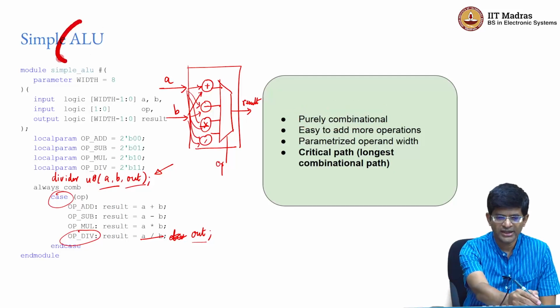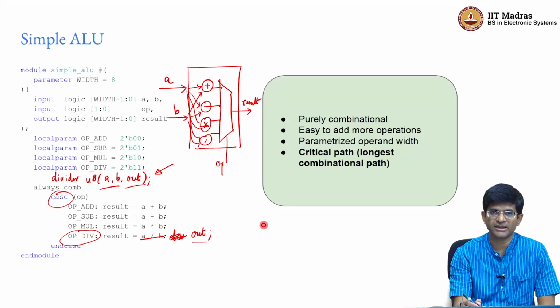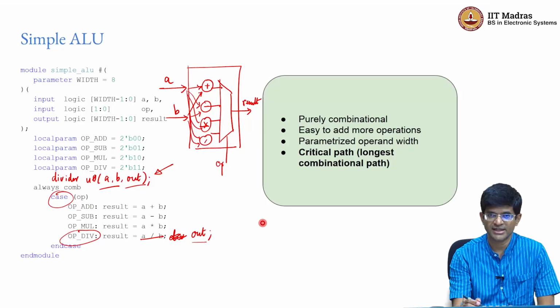In general we call it an ALU or an arithmetic and logic unit, because very often certain kinds of logical operations, what I mean by logical operations are things like shifting, shift left, shift right, and certain kinds of comparisons, or certain kinds of actual Boolean logic operations like AND, OR, XOR, or even just NOT, which is inverting a set of bits.